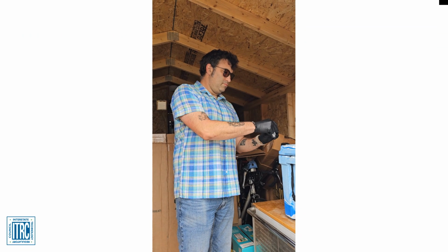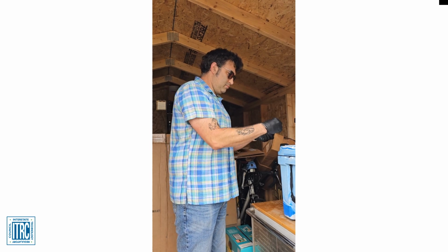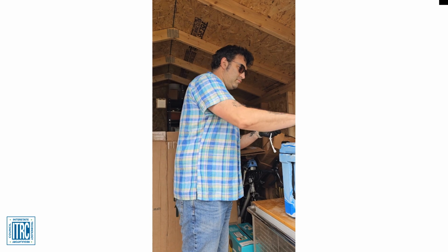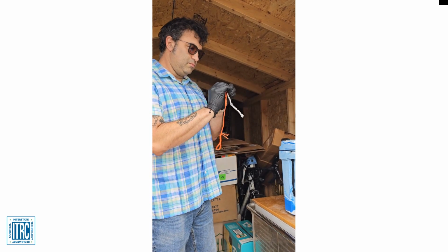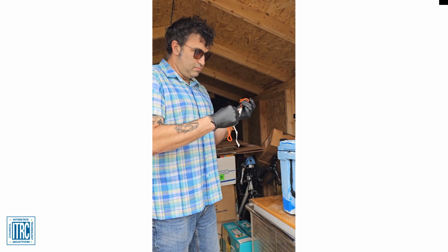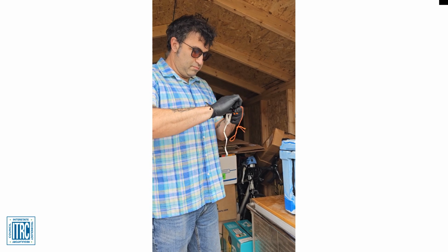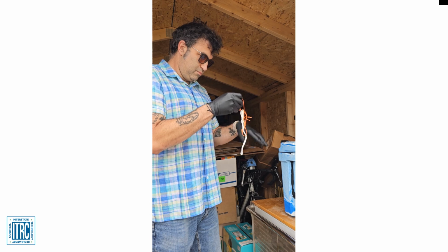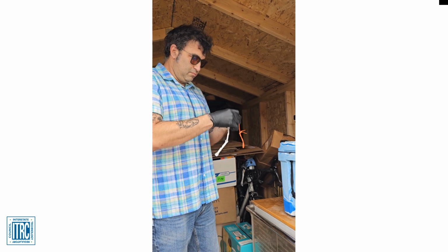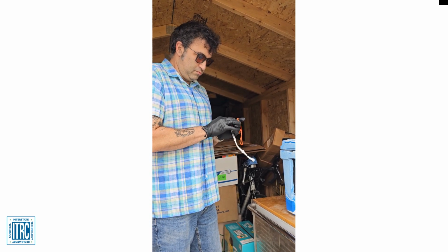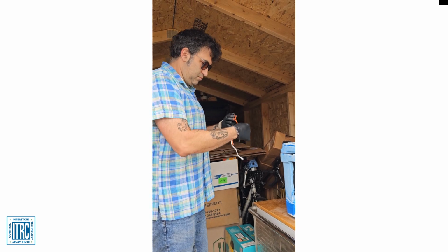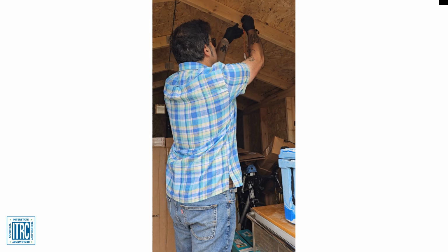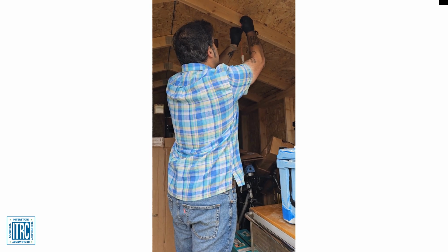When deploying the AGI sampler to collect indoor or outdoor air samples, follow these steps to install the device. Before going out into the field, verify that the sampling kit has all the necessary supplies and that the serial numbers on the samplers match those on the glass vials. And remember to take additional supplies and equipment needed for installation, such as pre-cut pieces of string, nails, or push pins. At each location, remove the sampler from its jar and reseal the empty jar. The sampler is then attached to the sample location using the predetermined method of hanging.